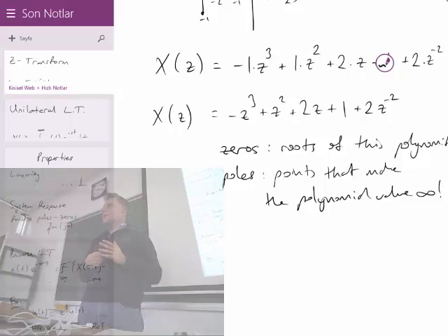Now, you know convolution, right? How did we perform convolution? We were flipping around one of the signals and sliding over the other one, and the overlapping things are multiplied and accumulated, and with respect to the shift, you assign the values of the convolution output, let's say y of n. Now, there is another way of understanding what a convolution means, and it comes from the convolution versus multiplication property.